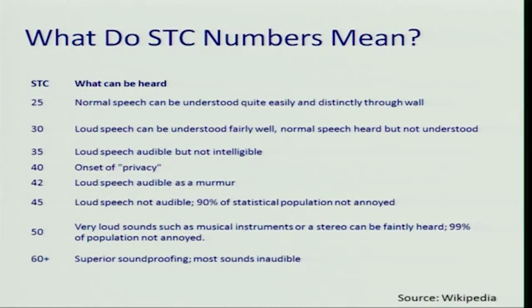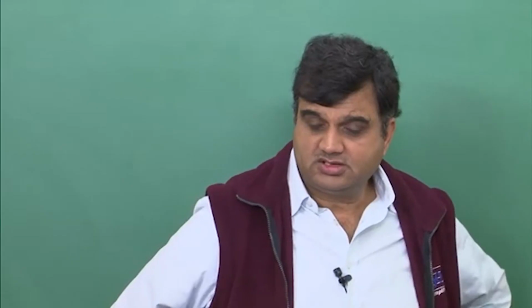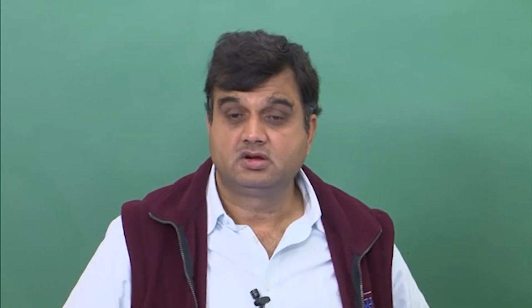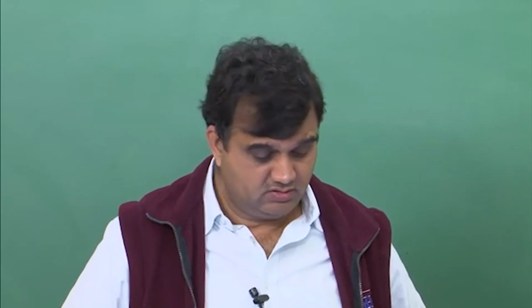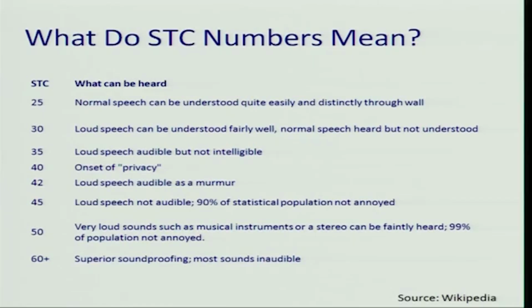If you go to STC 35, then the same door, if there is loud speech on this side, the person inside the room will be able to hear something. He'll say, okay, there's a discussion happening, but may not be able to necessarily figure out what is being discussed. If STC becomes 40, then not much is being heard. So whatever conversation is happening in this room remains private.